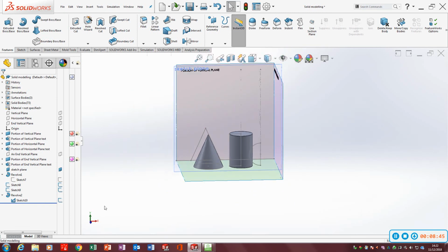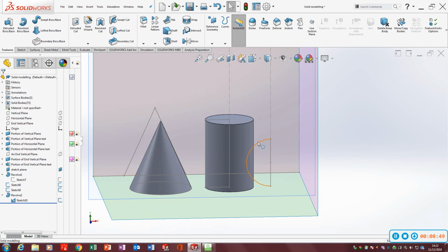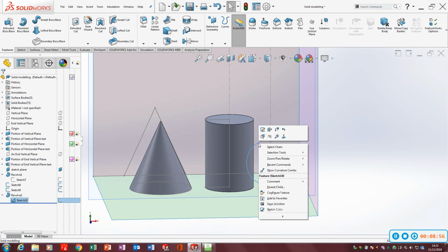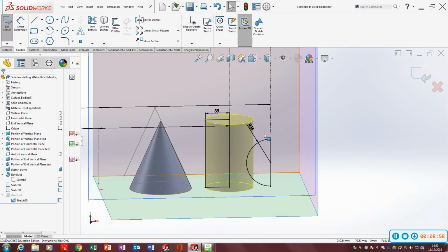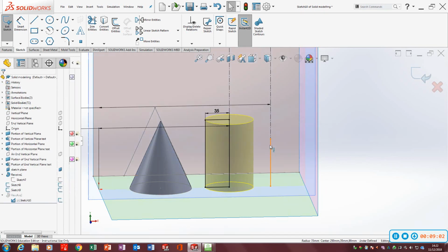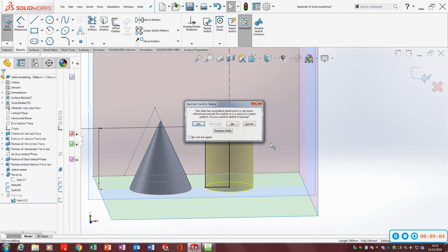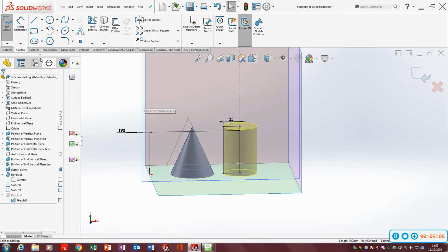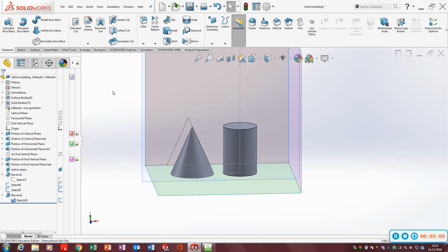Because it overlaps there with the sphere, instead of us exiting that sketch, we're actually going to just right click and get rid of those two there. So just click it, delete, so it doesn't run into your sphere. Alright, exit sketch, save your work regularly.